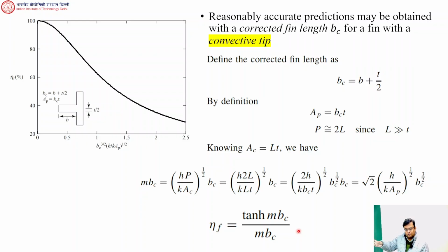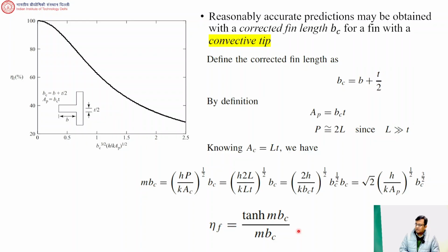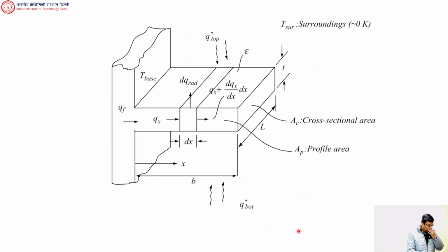Because if you have quite a high value of heat transfer coefficient, then maybe you don't even require fins. That's why when you have flow in a tube, with water flowing inside and air flowing outside, you place fins on the air side, because on the air side the heat transfer coefficient is smaller, correct? Now, typically in many cases you have natural convection, you have low heat transfer coefficient. That's why you are adding fins, but then radiation can also come into picture. So let's look at a situation like this.